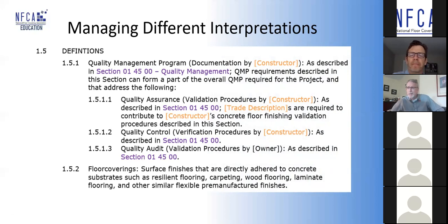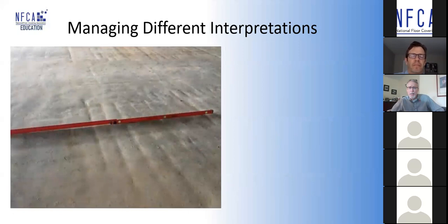The words flat, level, even, smooth were being used interchangeably for different things. What we found was that the same word was being used differently between the concrete trade and the flooring, floor covering trades. So the same words have different meanings when read by different people. The maximum floor straight edge tolerance requirement for floor covering from many manufacturers is 5 millimeters in 3 meters. Some of those can get down to 1.5 or 3 millimeters, or 2 millimeters in 3 meters.